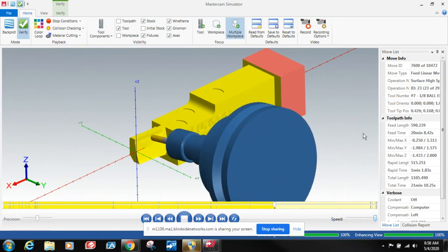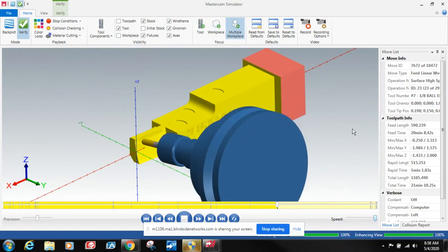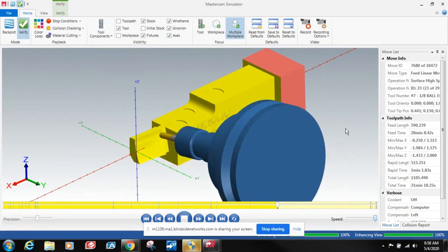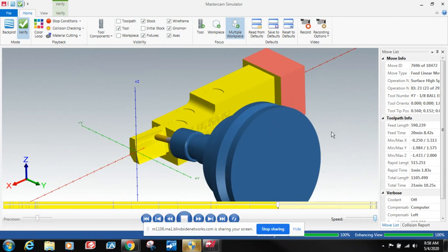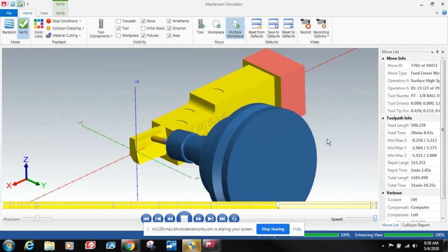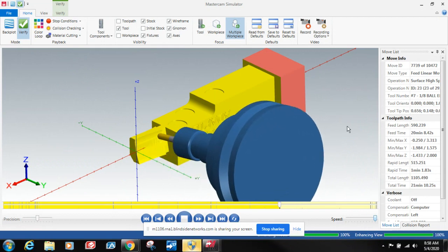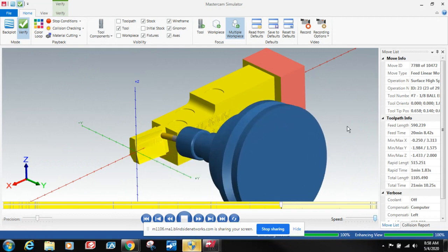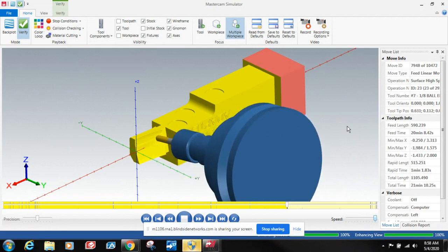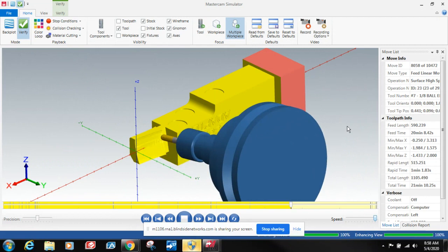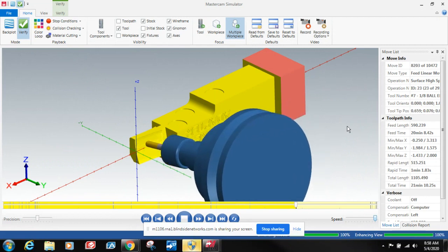So I'm guessing you have one plane that you're not using at all? Like that back plane? Well, that's your world coordinate system, so we leave that alone. That's set through the center of the part, so that's going to be your work coordinate. When you set this job up, we're going to set X, Y, 0 right through the center of the rotary.